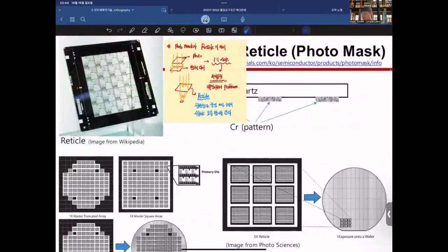And in the exposure step, we expose our light through the reticle and photomask. Photomask and reticle are a blueprint of what we plan for the semiconductor. So light goes through the reticle and shapes the wafer.